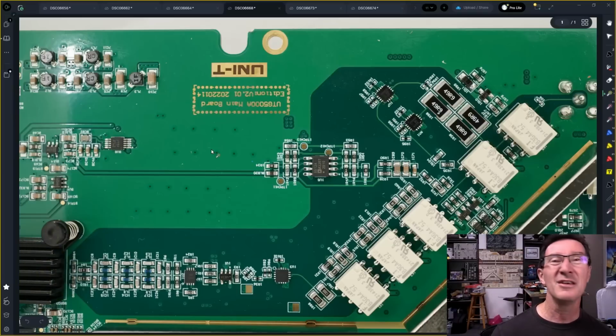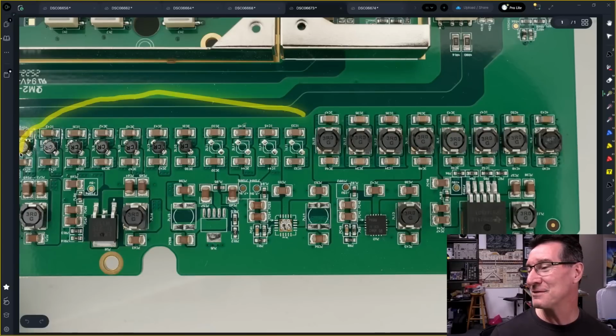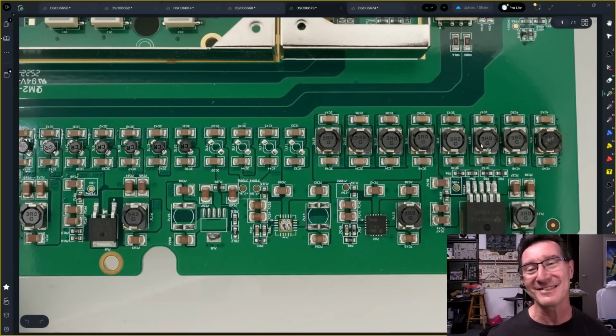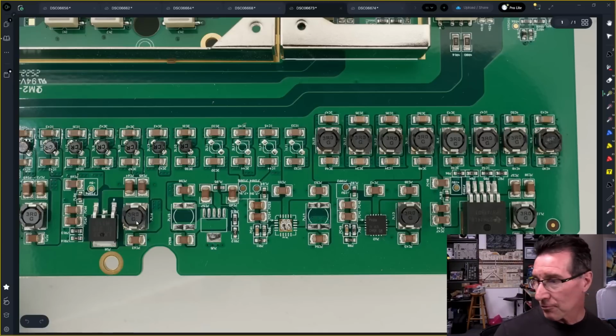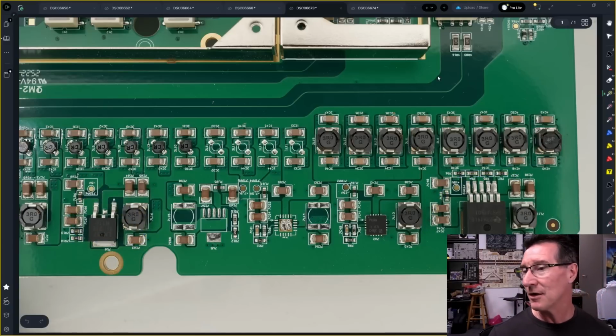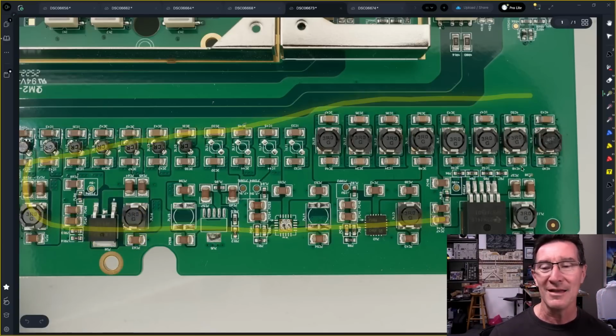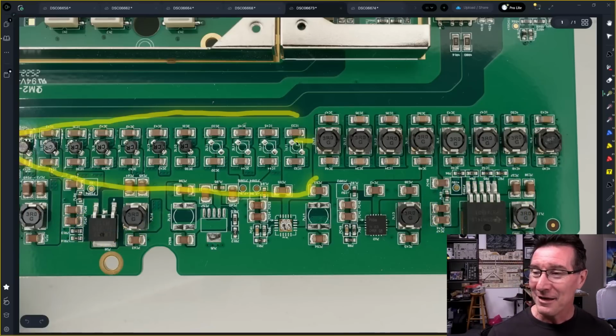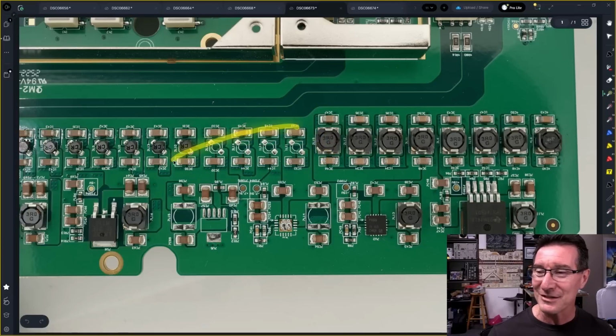So yeah, neat layout. And I just love all this multi-stage filter in here. Oh, this is just pornographic. It really is. So they really want to filter out those. They would be for the analog relays. We've got an LM337 over here. We've got another jobby there. I can't remember if I included that in the spreadsheet, but yeah, these are really just Joe Blogs regulators, but they really wanted to filter the absolute crap. They've left out a couple of inductors there, but they decided, oh, I'll keep the caps in, and there's a couple of extra filter parts missing here.